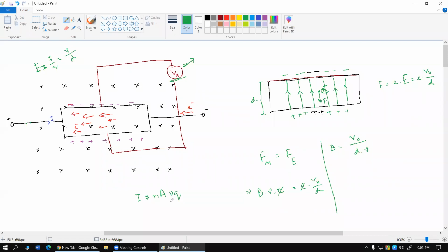Electron density, number of free electrons per unit volume. Beautiful. Number of charge carriers per unit volume. In this case, we can also say number of electrons per unit volume of this metal strip. A was the cross-sectional area. Cross-sectional area happens to be the perpendicular area with the current flow direction. This is very important because whenever I am considering cross-sectional area, current over here is flowing in this direction.